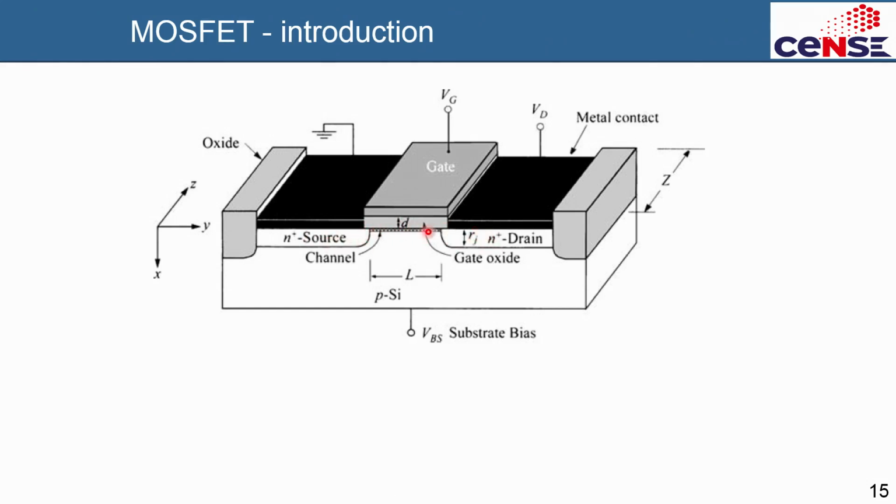This is a channel that is formed, which is basically the inversion channel that we have learned till now, and this is the oxide, this is the dielectric there. So don't worry about that. Everything looks the same, except that now don't worry about this oxide, this is an isolation sort of thing. We will not worry about that. You see this is a metal contact on the source. Of course the gate also has a metal or a polysilicon or whatever, and the drain also has a metal, this black colored here. So this is an N plus very highly doped pocket, like a source, and this is also an N plus highly doped pocket, like a drain, and this is the p substrate, and the channel is inverting